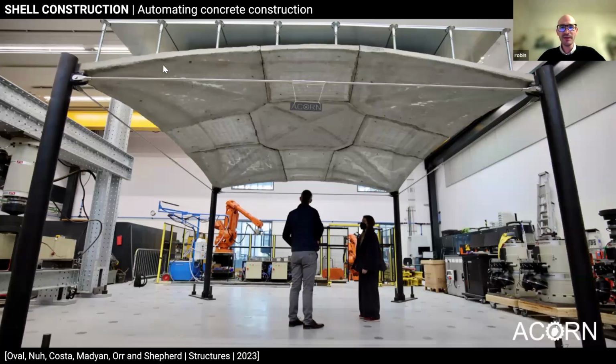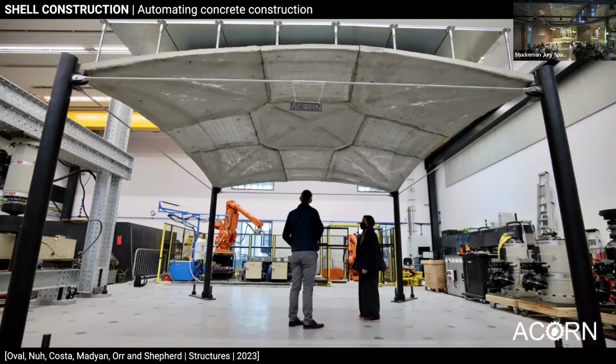We only have very shallow ribs, and it's not flat, it's curved, but the aim was again to address how can we reduce the environmental impact of our built environment. So in that case, again, building floors of concrete blocks. Why vaulted floors? Because they can be extremely thin, so funicular structures, as we saw at the beginning. So in pure compression, which is the most efficient way to use a material like concrete, more particularly. And how can we actually make sure we don't have to destroy it, but we can actually disassemble it?